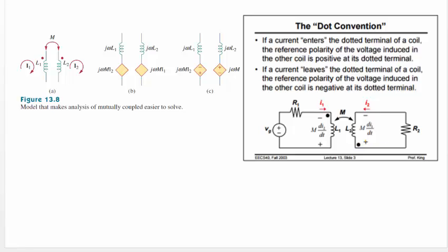So I put here a plus sign and a minus sign, and that's indicating the voltage that's induced on the secondary side. If I were doing a loop analysis around this circuit, I have additionally this induced voltage, where I hit a minus first and then a plus side.